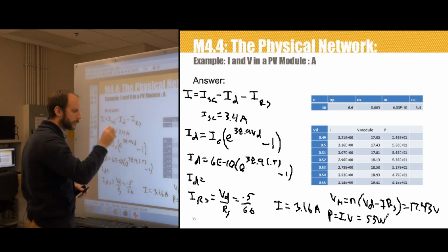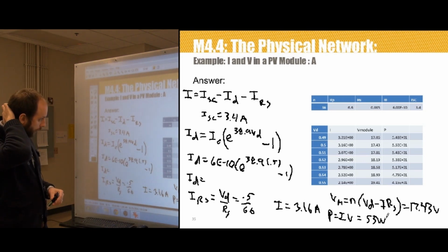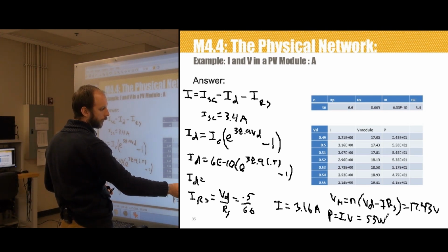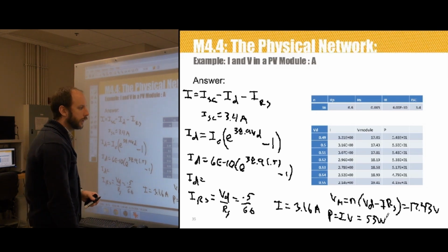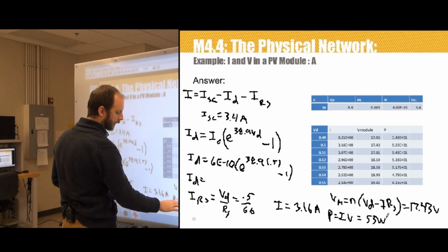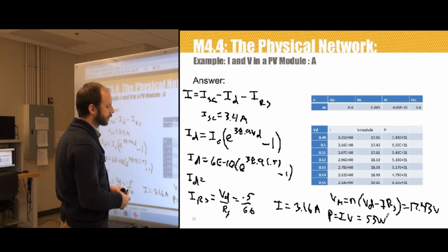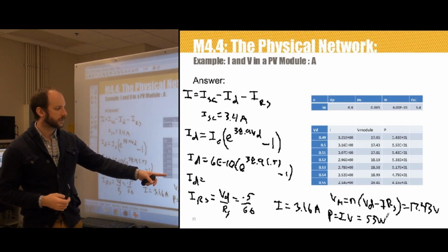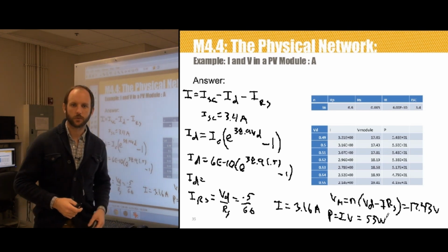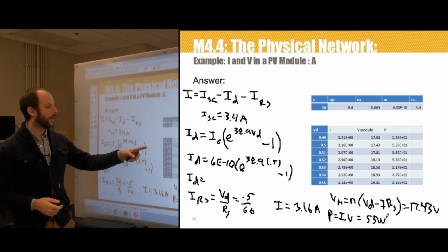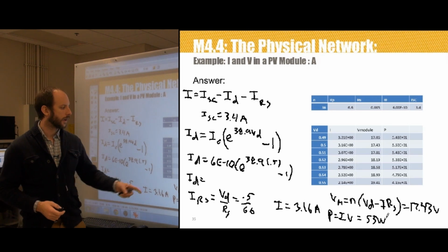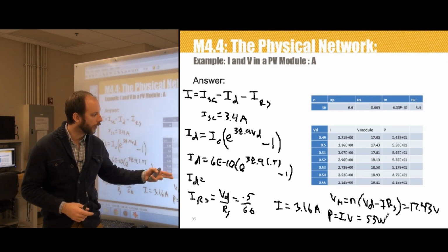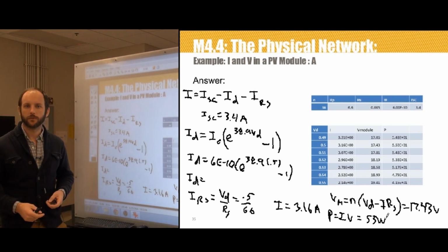So those are the results. The voltage of the module is calculated with this formula here, iterated, and then the power of the module is calculated here, iterated. So we can see that as the voltage across the diode increases, we have this different relationship that we would see. So we can plot a VD versus ISC plot if we wanted to for this, or a V module versus ISC plot for that if we wanted to.